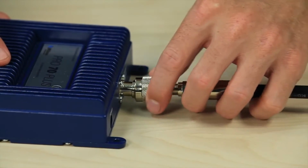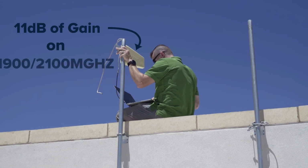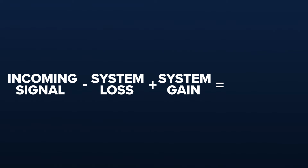Antennas each have a certain amount of gain built right in. The booster also supplies a certain amount of gain. For example, a Yagi donor antenna has 11 dB of gain on the 1900 and 2100 MHz frequencies. Add the gain from the donor and broadcast antennas to that of the booster and you'll have your total system gain. Take your incoming signal, subtract your system loss, and add in system gain, and you've got your output signal level.